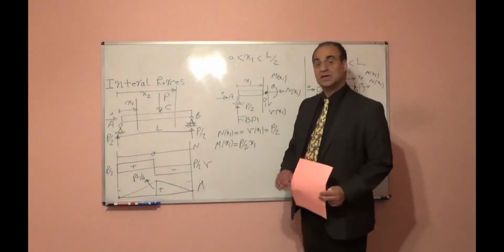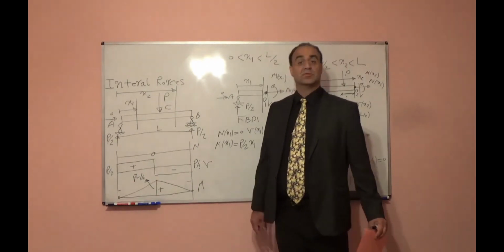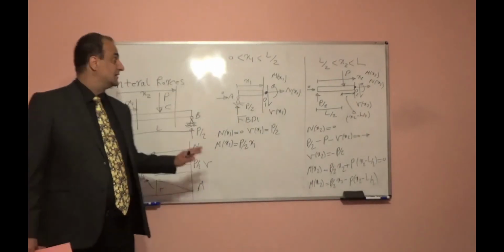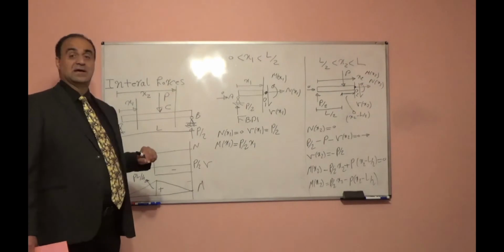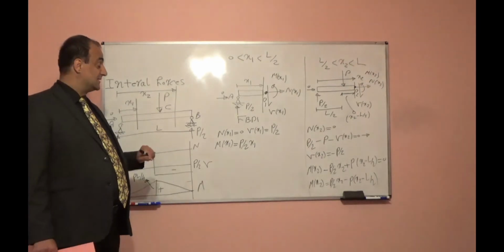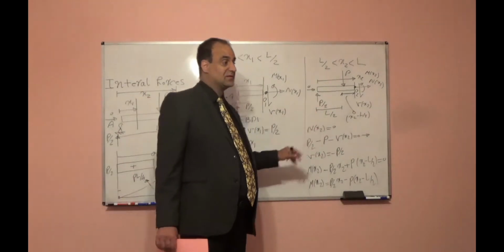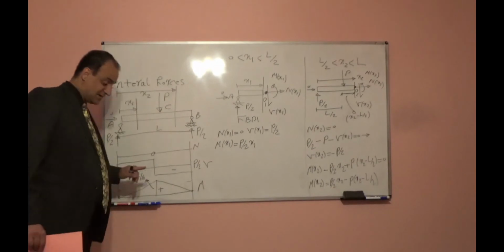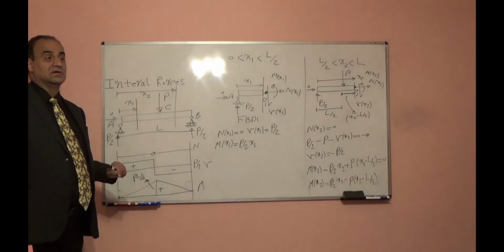This will be axial force diagram, shear force diagram, bending moment diagram. I drew using classical way, using free body diagram. You can practice and draw a little bit faster, but in the exam you should follow these steps, you should show it. But there is another method. Let's practice from the beginning. First I will find the reactions.